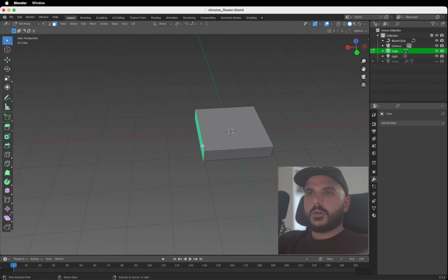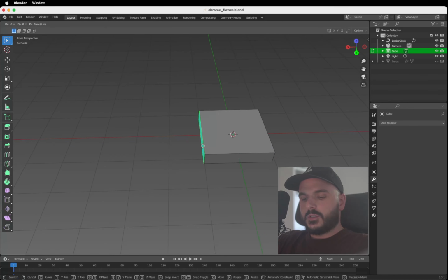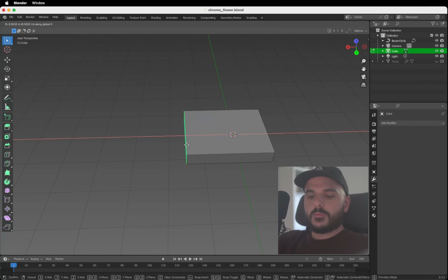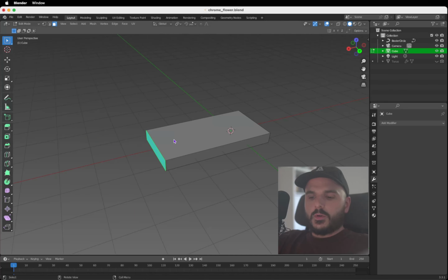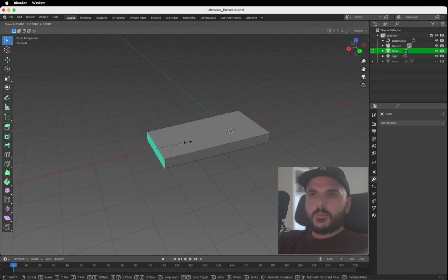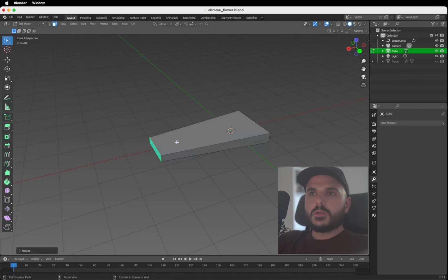And we take this face and press G and X. If you hit Control, you move in the scale. So let's place it around here. Now press S and scale it down a bit. You can hit Control again, somewhere around here. And now let's add 2 loop cuts.